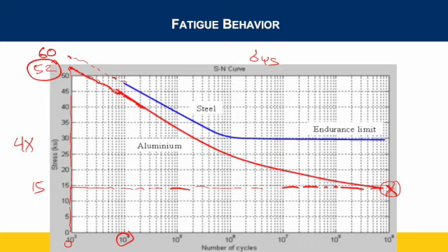And we see that a lot of times in steel. Steel does lose its yield strength, but then it reaches a point where all of the cracks get blunted out and the stress is no longer higher, and it reaches a limit. Okay? And this is really useful because if we engineer, say, the material to never go above a stress of 25, as we cycle it, the steel will lose stress, yield strength, but it will stop at about 30. And in this case, this amount of stress being applied to the steel would never break it.